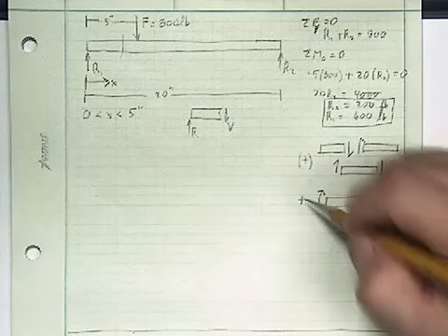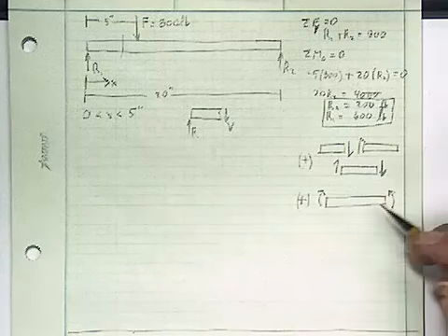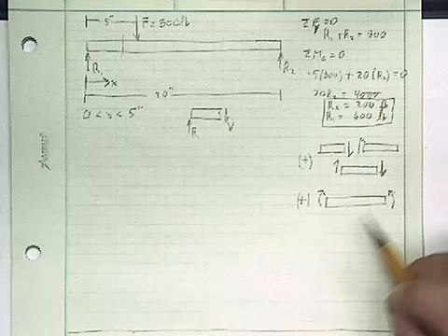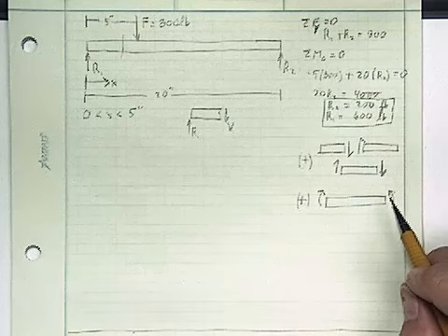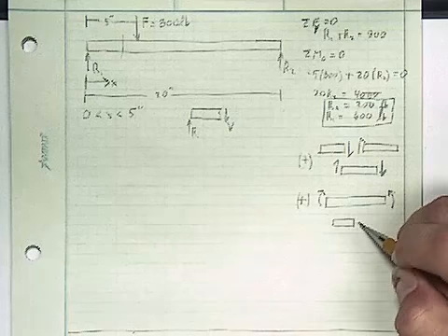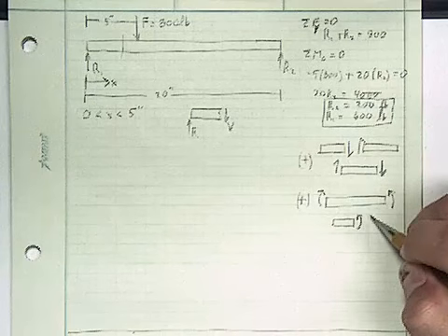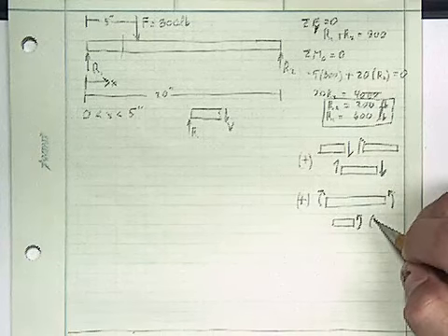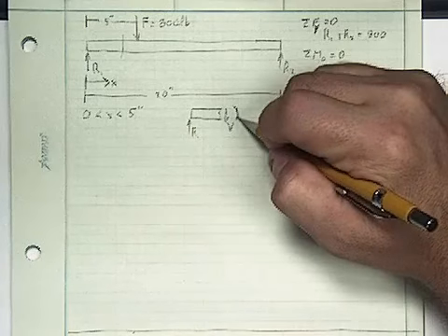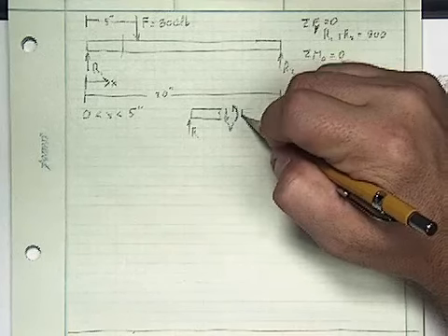I would rather say that it's holding water, but however you want to say it. Convex is holding water versus the negative would be shedding water. And again, if I look at this on the inside, if I were to take the break on the inside of the beam, this is also considered positive. So what that means is right here, there exists a positive moment. I'm going to call it M.